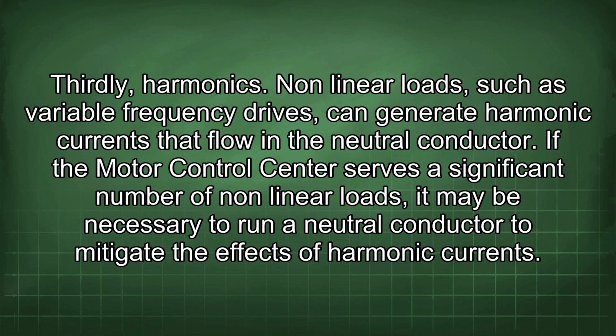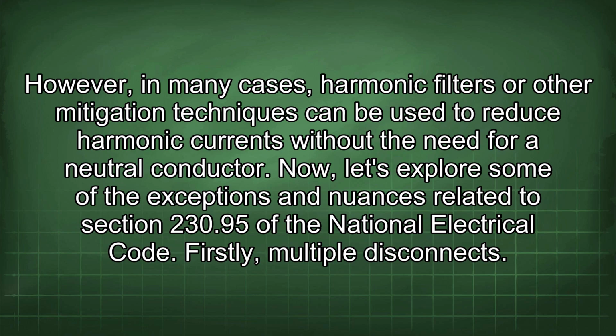Thirdly, harmonics. Nonlinear loads, such as variable frequency drives, can generate harmonic currents that flow in the neutral conductor. If the motor control center serves a significant number of nonlinear loads, it may be necessary to run a neutral conductor to mitigate the effects of harmonic currents. However, in many cases, harmonic filters or other mitigation techniques can be used to reduce harmonic currents without the need for a neutral conductor.